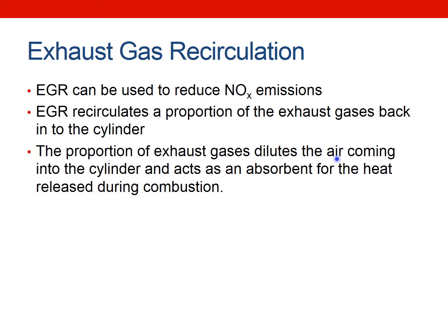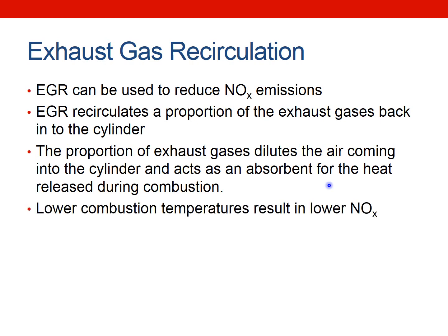So when you put in your air and you add some more fuel and you combust it, not only does it displace that charge, but it also absorbs the heat from the combustion process, reducing the combustion temperature, which will lower flame speed, but more importantly, it reduces NOx.